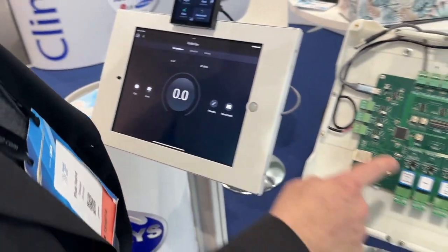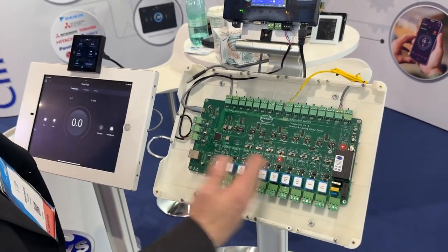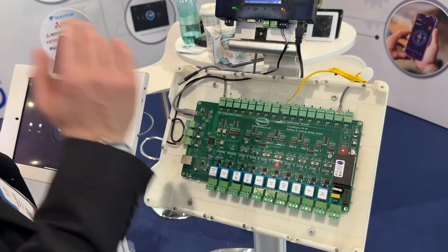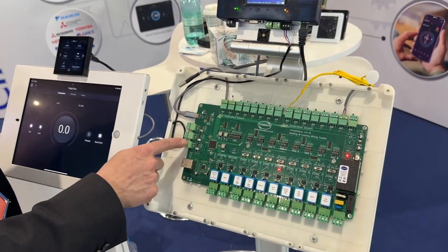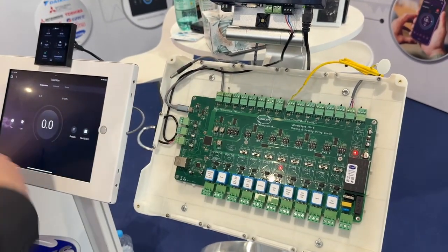On the ClimateSync, connected to Control4, you can control 8 zones, configure each zone individually, with room and floor limit sensors. There are 3 Modbus connections, which means on one of them you can daisy chain up to 16 of these boards back to a CoolMaster, back to Control4.